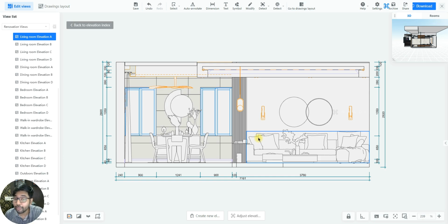Yes, you should also be able to generate a color drawing for your elevations apart from your line drawing. So for that, in the same window at the bottom here, can you see you have something called display mode, right? Click it. This will open up this tab, and here right now we are in the color wireframe, okay, which means your line drawing in different colors representing different components. Instead, you have something called realistic here, right?